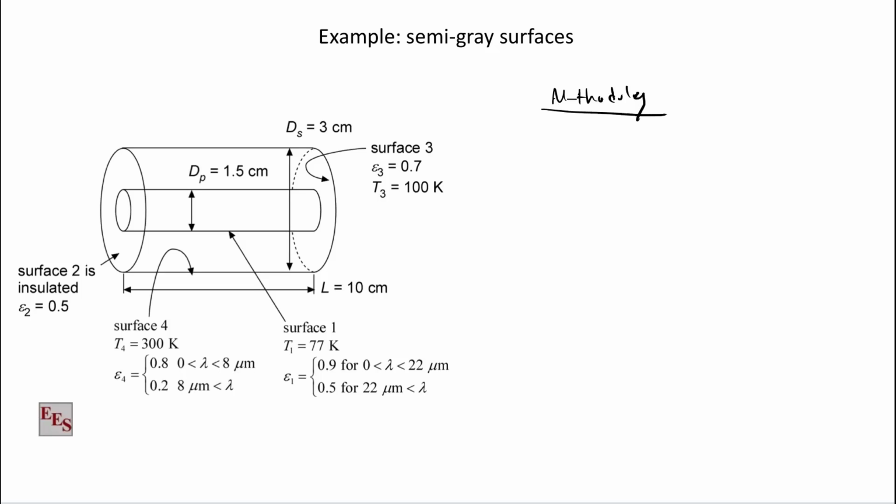The methodology is going to be, one, let's enter the emissivities. Enter emissivity matrix. Okay, instead of a vector here, we no longer have 4 emissivities, we have 4 surfaces with NB emissivities. We have a matrix of emissivities that we have to enter. Enter the emissivities. So two, we would do areas and view factors. We've already done that. Areas, view factors.